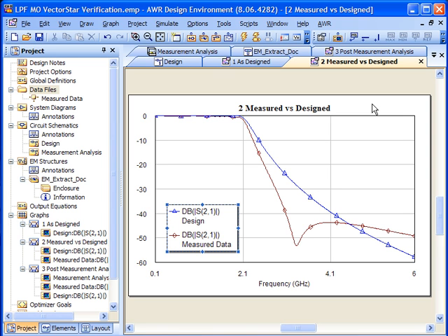So what's going on here? Well, we can take some guesses. Two very high probable events are occurring here if we look at our measured curve versus our design curve. First of all, we're using real components. 0603 parts, 0402 parts for surface mount passives have package resonances associated with them. And we see a little resonance here, right in the neighborhood where you'd expect to see these for some 0402 parts perhaps. Now, the resonance can vary based on the package size, based on the vendor, and based on the substrate material. We're measuring this on FR4.